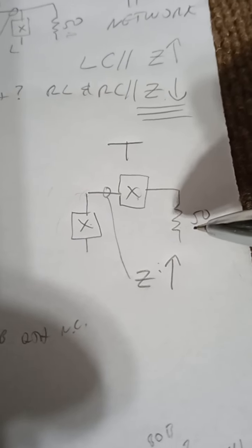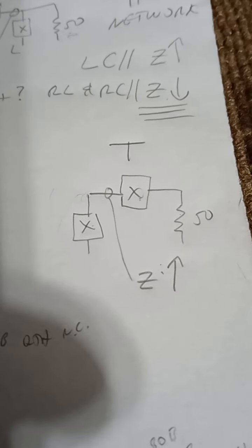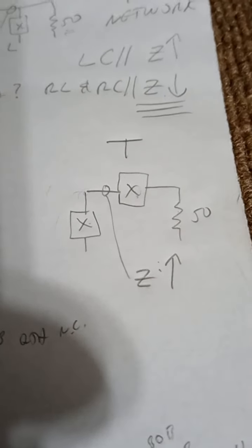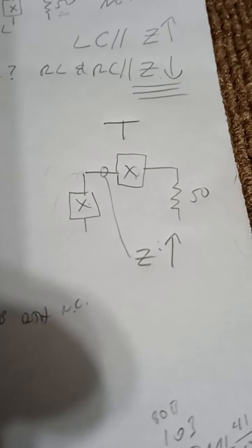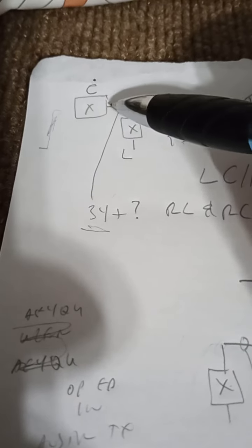Another thing to notice, there are some combinations of input-output resistance, frequency, component values that are just not workable. If you look in Radio Engineer's Handbook, this is all calculated based on phase angle, which is an assumption. Anything from 10 to 170 degrees. But certain values, for example, put these components very close to resonance. So a little bit of error in that network where these are close to resonance will really screw up the output. That's kind of a similar sort of problem with having that stray resistance here.